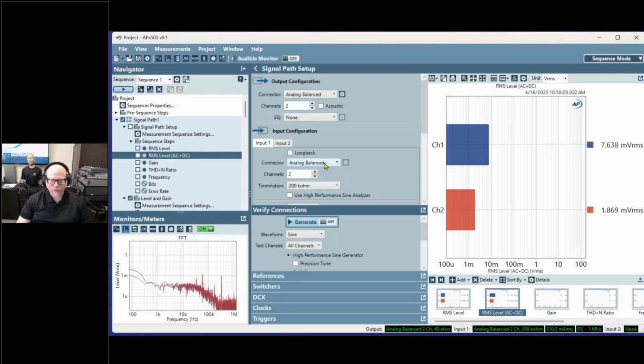So in the old days, most power amplifiers were single-ended devices. That is to say, there was a terminal referred to ground that contained the signal. Much more commonly today are differential or bridge mode amplifiers, where you have two terminals swinging relative to each other.